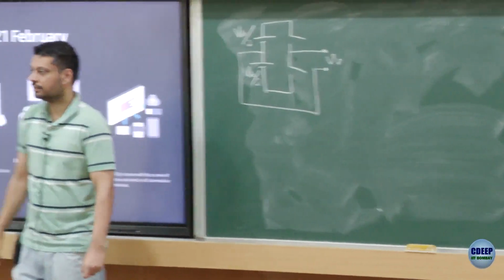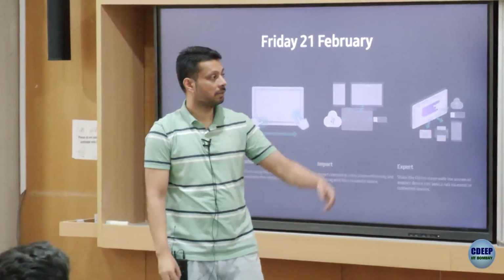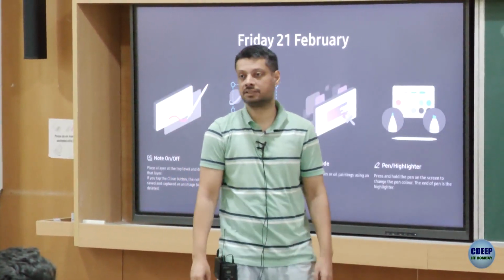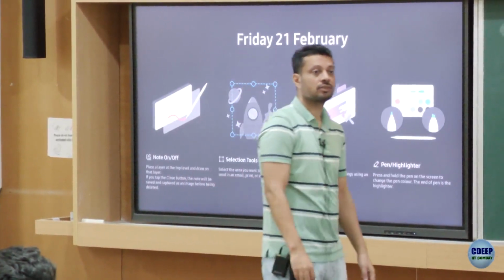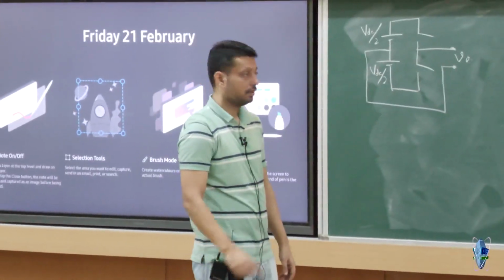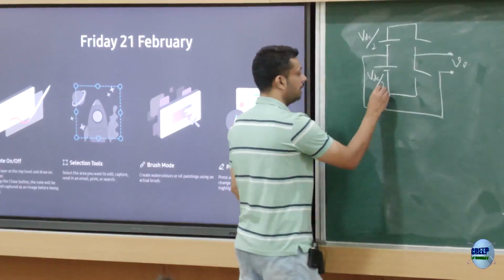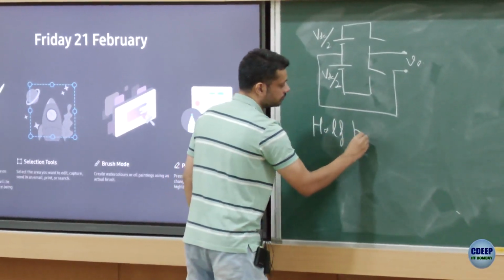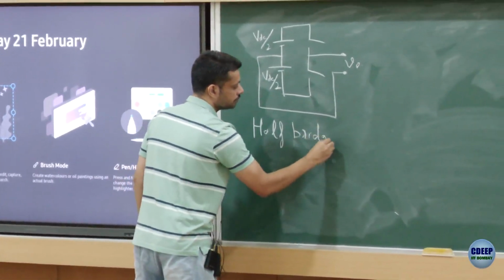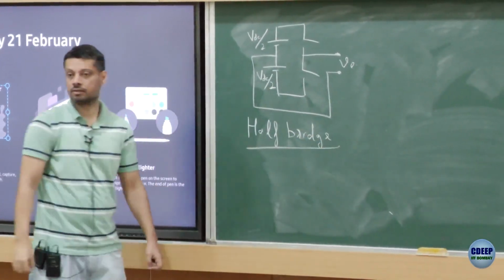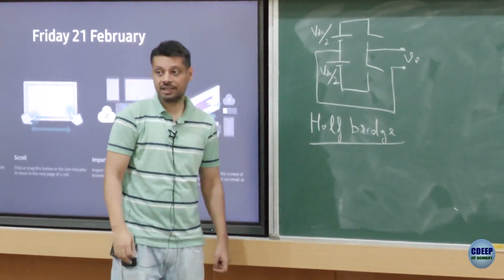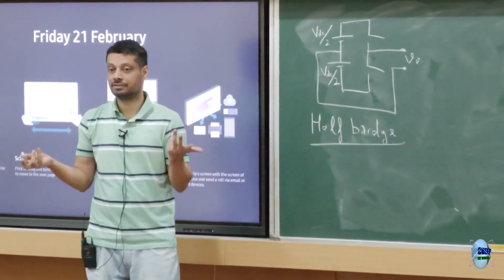This is another inverter. The one on the left, which we saw before, is called a full bridge, or H-bridge. This is called a half bridge. In this case, unfortunately, you don't have any zero state.